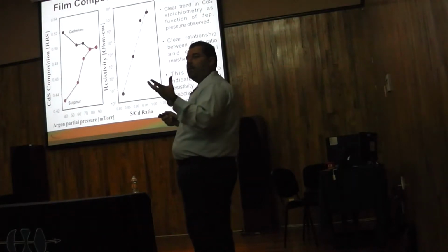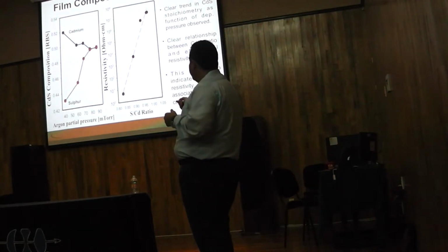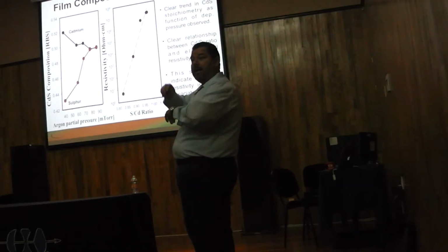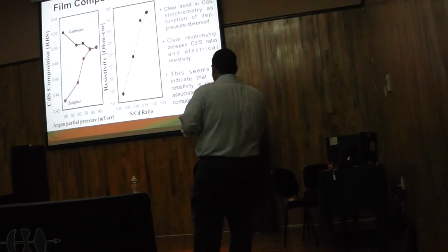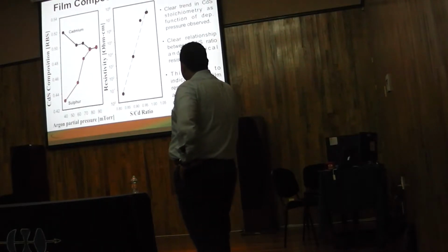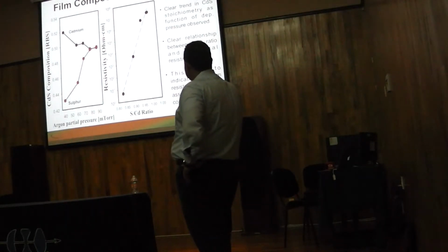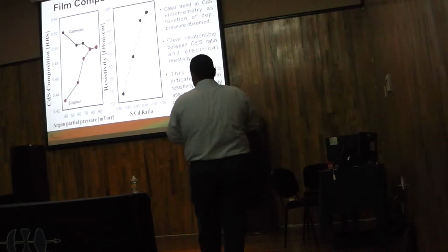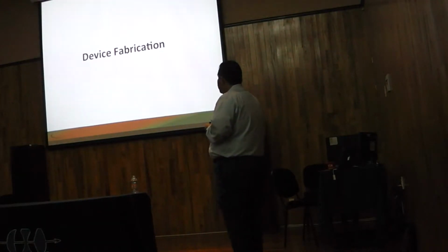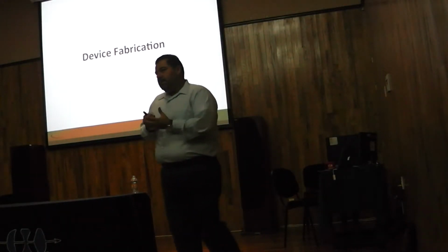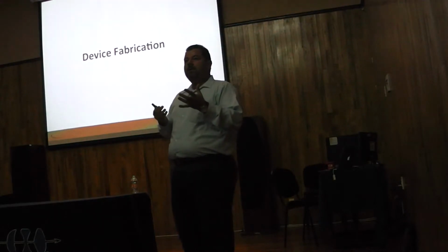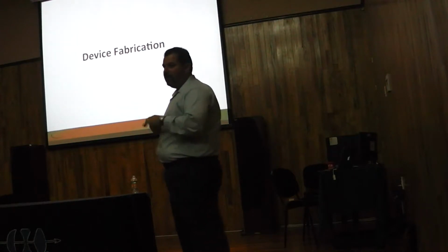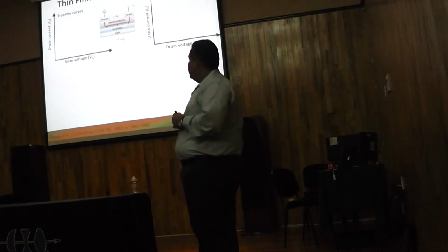And what will be really great for us is to collaborate with the institute to find where the sulfur vacancies or the cadmium vacancies are located within the band gap of the material, or if we have other defects. And if you plot this on a log scale, resistivity versus sulfur to cadmium ratio, it is an almost linear relation, which makes clear that that's indeed what is happening. Once we understand all these concepts in the material, then we go and make devices. If you try to make the device without knowing the material, good luck. It's very, very difficult. Okay?